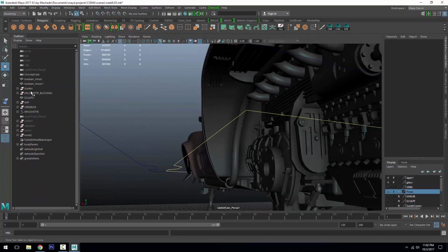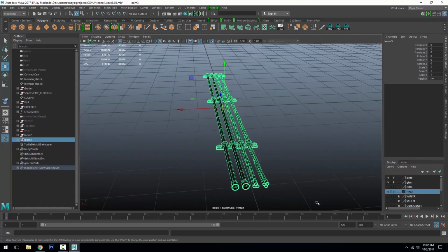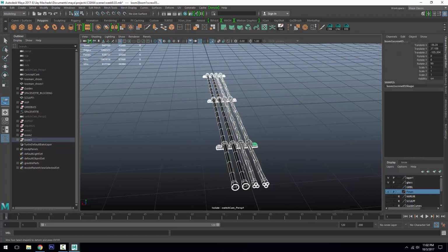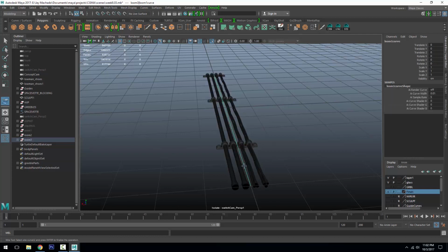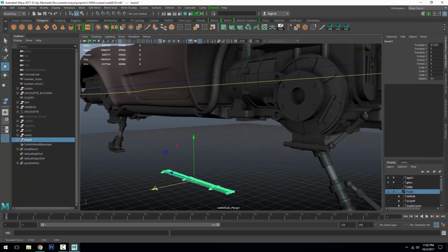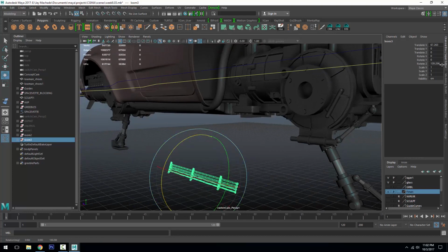Let me go back and I'll duplicate this and unhide it. And now let's set up the next wire deformer. So deform wire, grab everything except the curve, press enter, grab the curve, press enter. And last step is set the drop-off distance to 100. So now I'm ready to pose this other one. Let me rotate it around this way, 180.